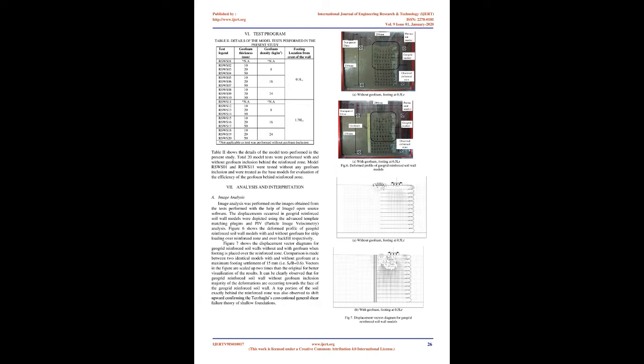The wide-width tensile strength of the geogrid was found to be 3.8 kN/m at an ultimate tensile strain of 24%. C. Geofoam. Expanded polystyrene, EPS, geofoam was used in the present study as a compressible inclusion behind the reinforced zone. Three types of geofoam were used: F1, F2, and F3, with varying densities of 8, 16 and 24 kg/m3 respectively. The compressive resistance in uniaxial unconfined compression tests was found to be 17, 42, and 74 kPa for geofoam F1, F2 and F3 respectively.